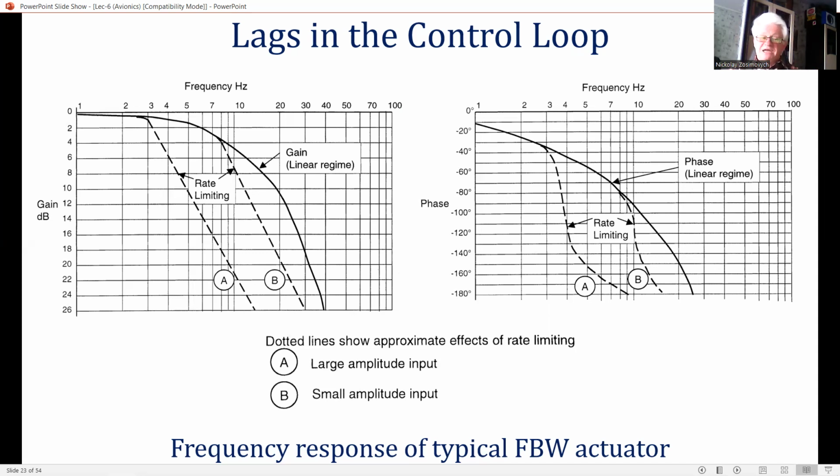Sensor dynamics. The sensor dynamic response may need to be taken into account, depending on the type of sensors used. For example, angular momentum rate gyros of the two-axes dynamically tuned type, DTG, have torque balance loops with a bandwidth in the region of 60 to 70 Hz.